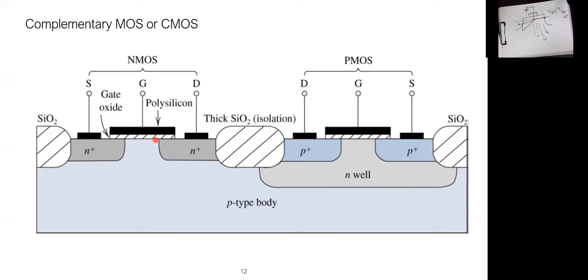On the other hand, you can have what we call a P-channel MOSFET. Herein, your substrate is N type, your source and drain are P type, so you are requested to put a negative voltage on the gate to attract holes in the channel and create your P channel.